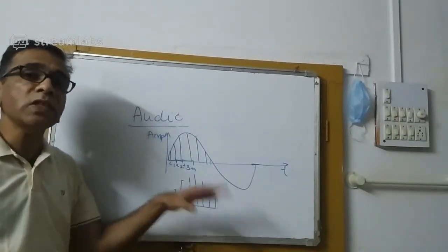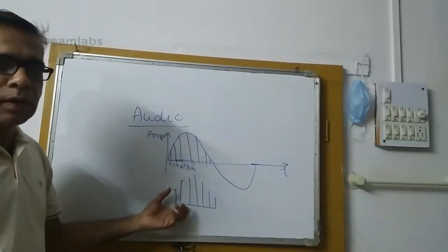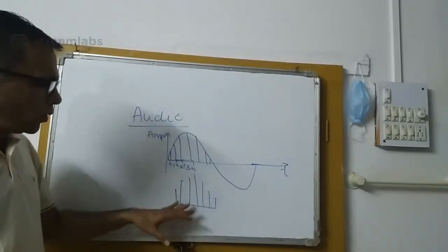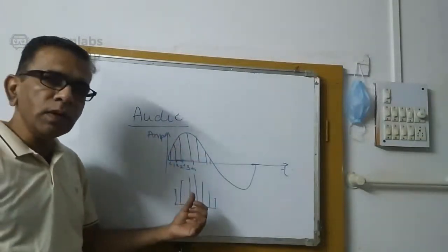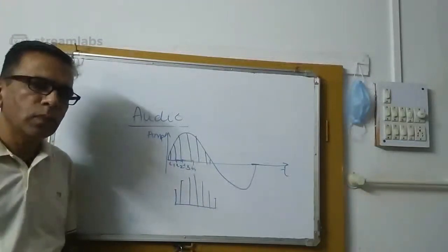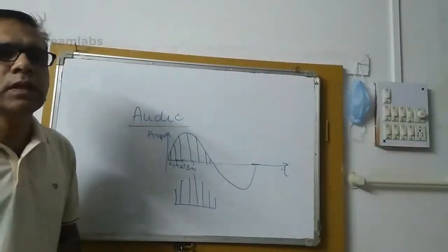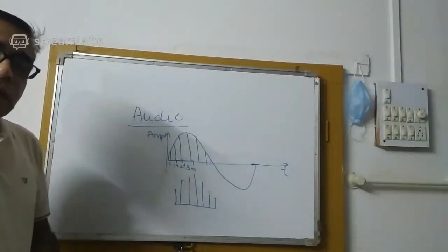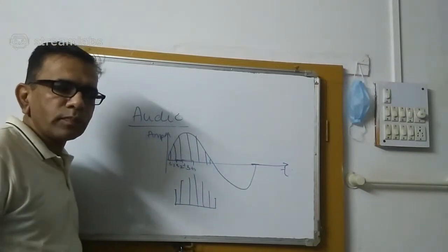This is the first step involved in representing this audio in digital form. Again, the samples we have collected at different time intervals are of a very wide range, so it is again difficult to represent them in digital form. For that reason, we use one more step, the quantization step.